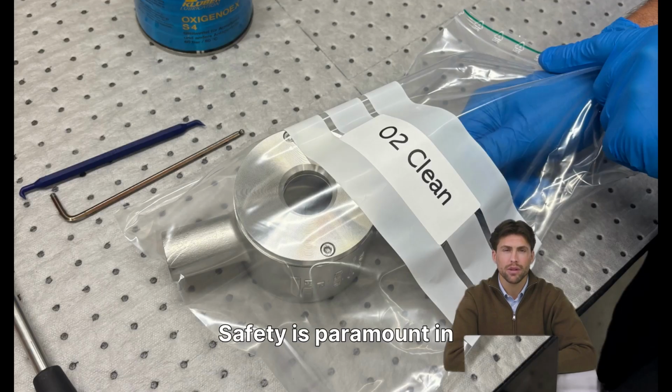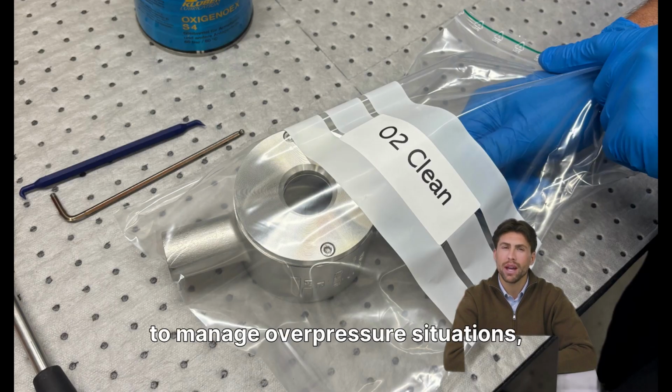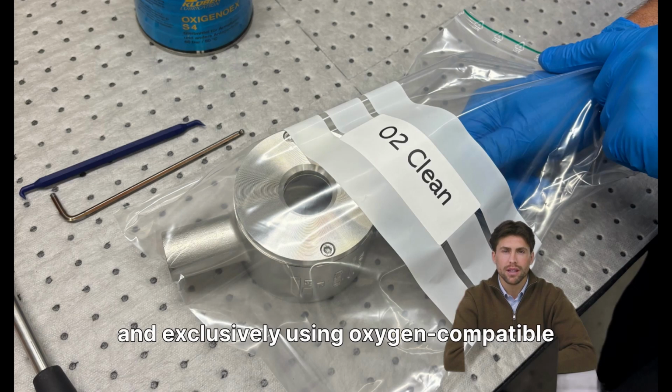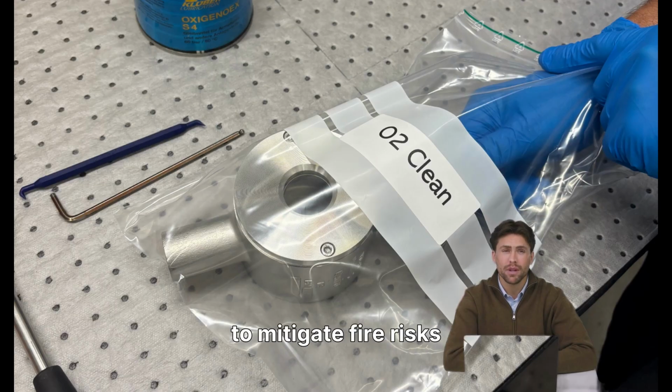Safety is paramount in a merchant oxygen plant due to the nature of the materials handled. Strict protocols include ensuring all equipment is thoroughly degreased to prevent combustion, installing pressure relief valves to manage overpressure situations, and exclusively using oxygen-compatible materials throughout the system. These measures are critical to mitigate fire risks and ensure safe operation.